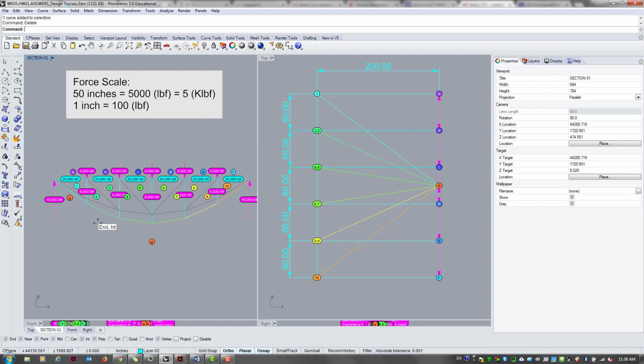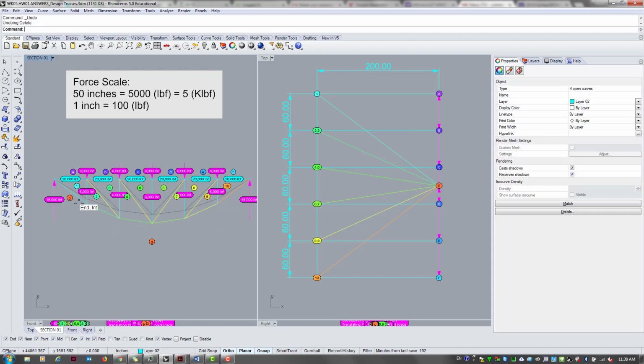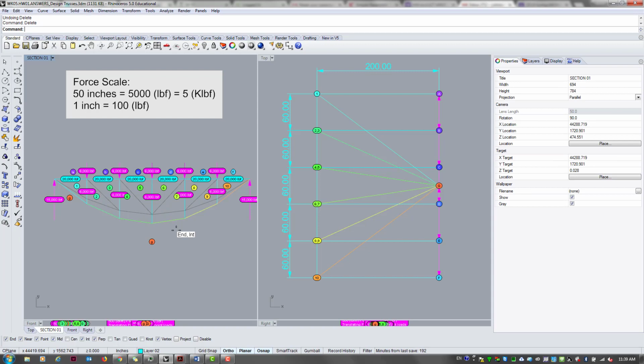And the reason why this kind of efficiency is possible is the bottom part is pretty much what is called a funicular curve, right? It's basically the same thing as this hanging cable. So this truss is basically this compressive stick with constant force in its entire length, and this tension cable at the bottom, and then compression struts in between, right? It's kind of like a bow. You take a bow and you put a bunch of struts in between, fixing the bow at that point.